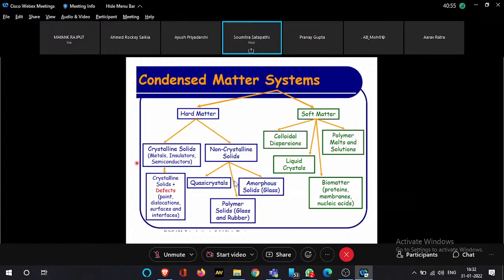So in the case of the insulator, it is not very easy to excite an electron from the valence band to the conduction band. Now, you can ask how I can get the electron from the valence band into the conduction band. To do that, we have to provide some external energy. This external energy can be heat energy, magnetic energy, or light energy. When the electron absorbs this energy, it excites and goes from the valence band to the conduction band, and once it is in the conduction band, it starts participating in the electrical conductivity. For the case of an insulator, it is not that easy for the electron to go from the valence band to the conduction band.